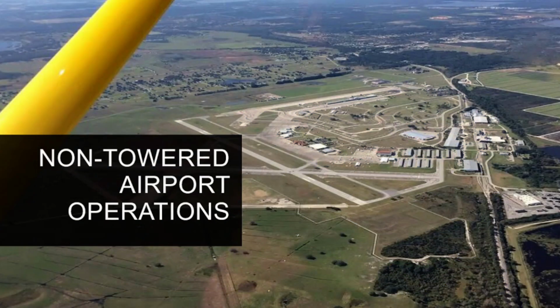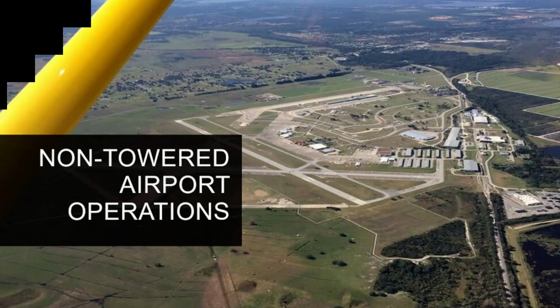Departures from airports without an operating control tower. There are hundreds of airports across the United States that operate successfully every day without the benefit of a control tower. While a tower is certainly beneficial when departing IFR, most other departures can be made with new challenges. As usual, you must file your flight plan at least 30 minutes in advance. During your planning phase, investigate the departure airport's method for receiving an instrument clearance.